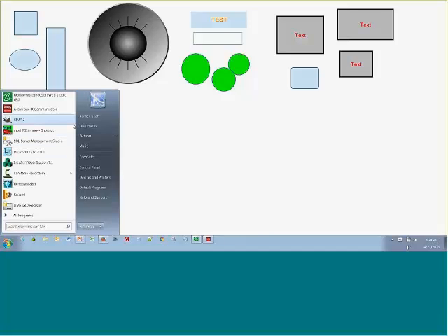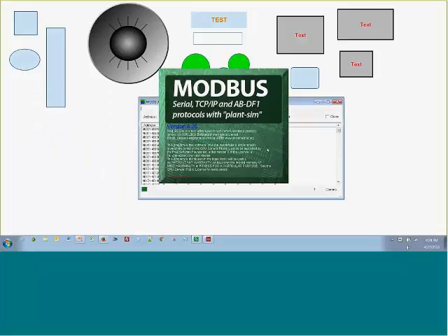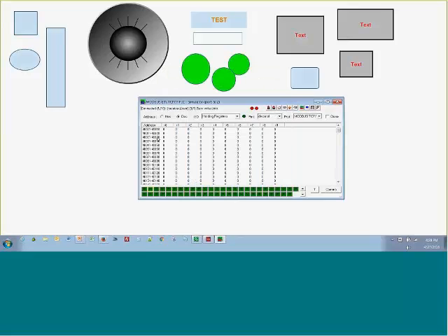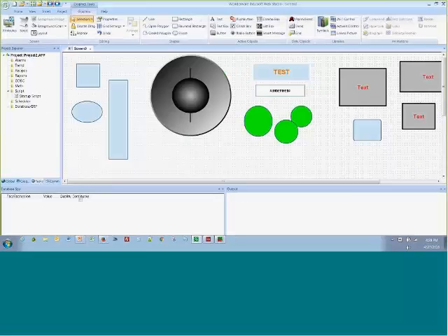And once we do that, we'll get some values in. This is not an InduSoft product. This is just a third-party thing that I found on the internet. And so now you can see here this is changing, and that bar graph is going up. And it just used that tag definition to point to that IP address.